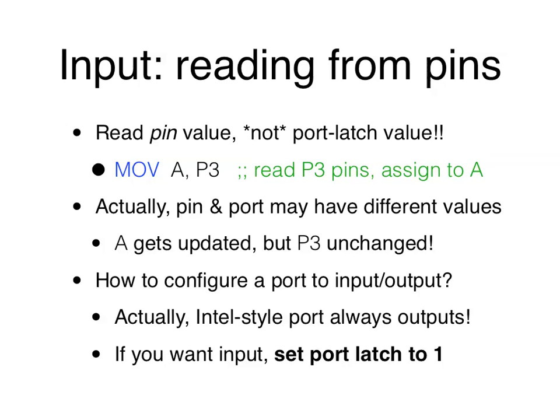At least on 8051, if you want to input, first set the port bits to 1, and that's safe. If you leave it at low state or 0 volt, there's a chance you can burn something up. So be careful with this. And we'll go over some of these concepts again next time.